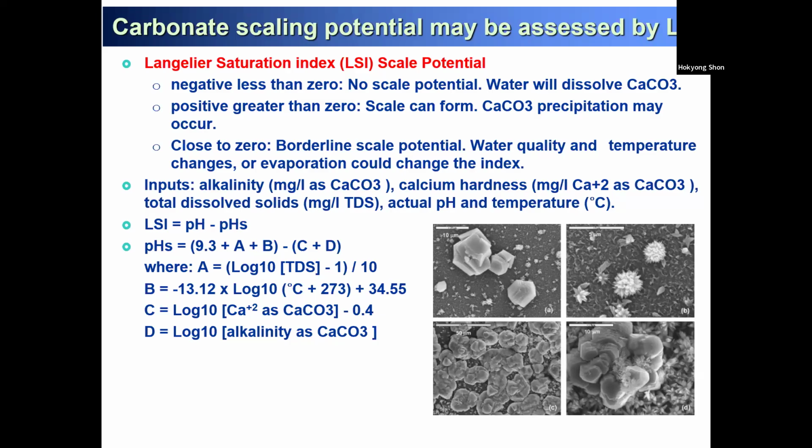So when you see the red color in your report, you have to go back. You have to change the pH, the temperature. You need to also change some other calcium and alkalinity concentrations, which can reduce this kind of inorganic fouling on the membrane surface. This will happen when you concentrate your seawater more and more through desalination, and then this will continue to increase.